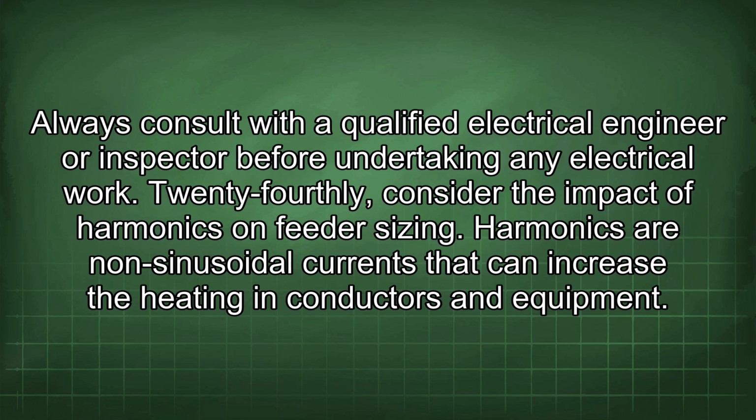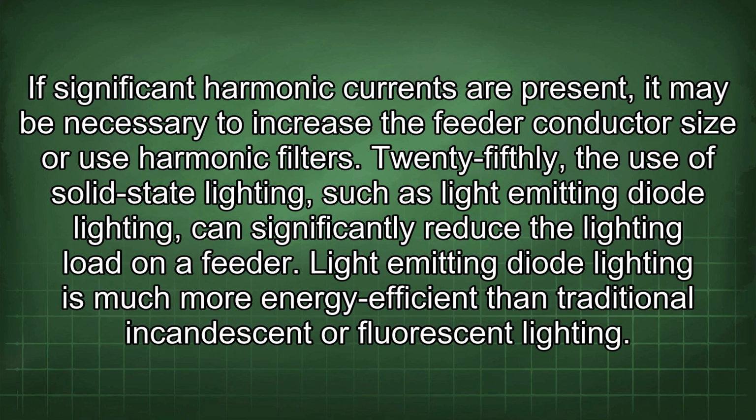24thly, consider the impact of harmonics on feeder sizing. Harmonics are non-sinusoidal currents that can increase the heating in conductors and equipment. If significant harmonic currents are present, it may be necessary to increase the feeder conductor size or use harmonic filters.